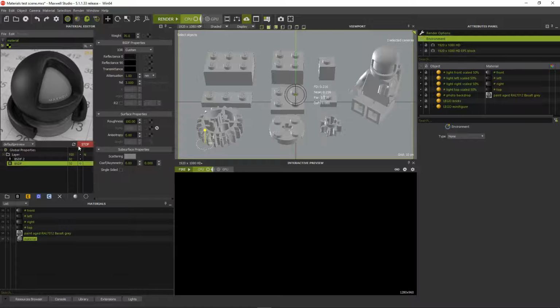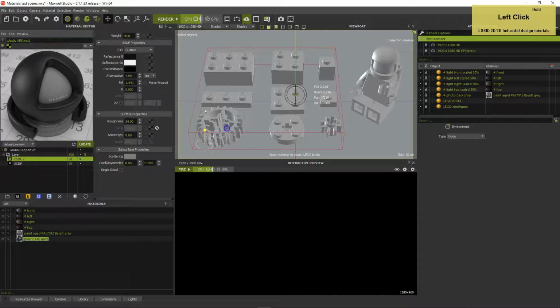Because of the size of the symbol and its baked-in UV coordinates, and your objects having different dimensions and wall thicknesses, it is best to use the relative texture mapping method and keep repeat and bump strength as shown, not for the render, but only the preview icon. Drag the material onto bricks and minifigure, then click Render.